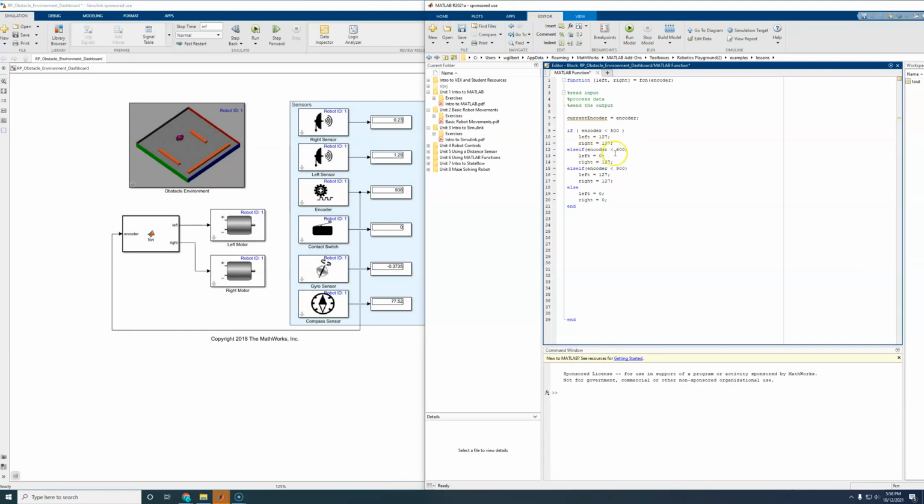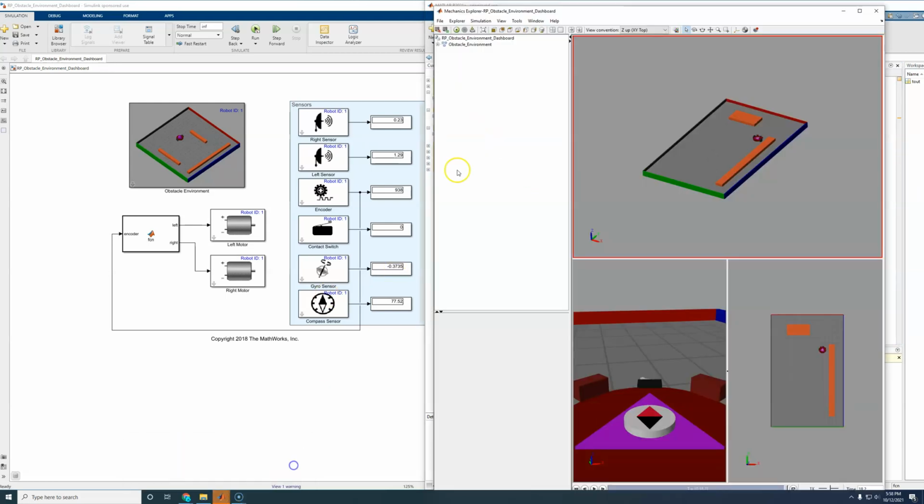We need to add a few more ticks to this. So let's up that to 610 on the turn, and let's up this to 1,000. Save it and run it. Now, hopefully, again, if y'all are doing math on yours and you know your distances, that will take away some of your trial and error. That's a much better turn. Looks like we've got a better line.